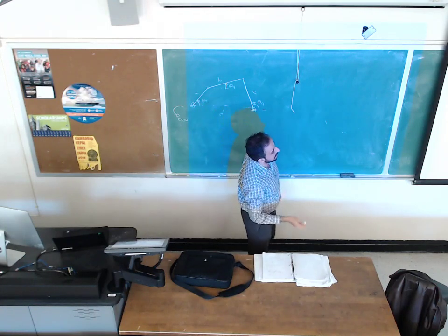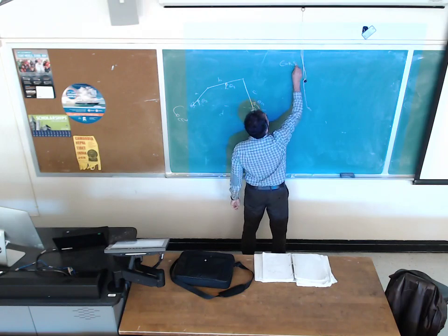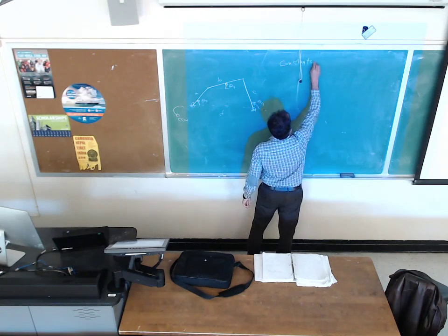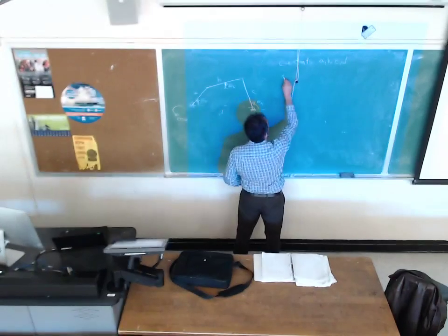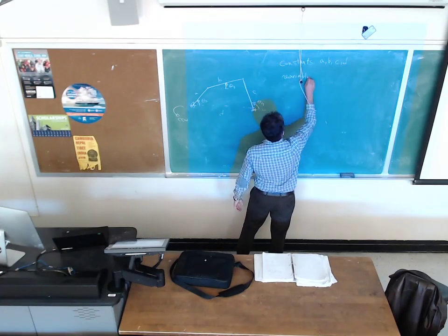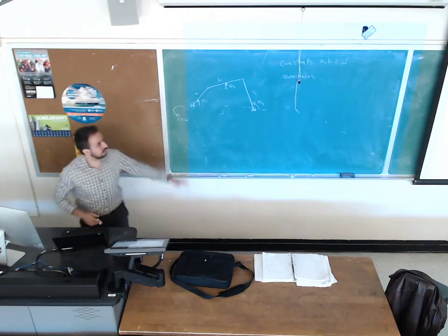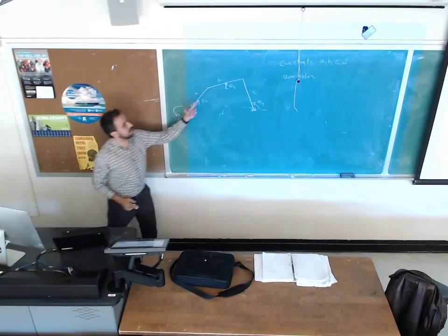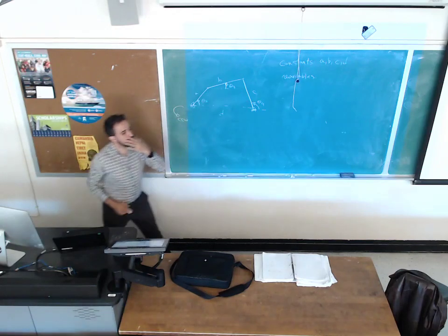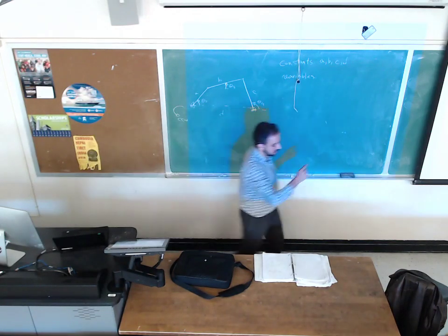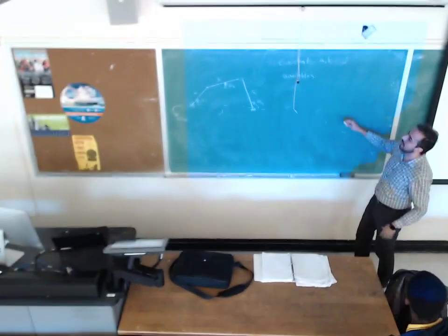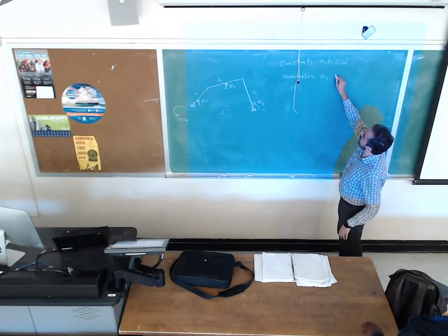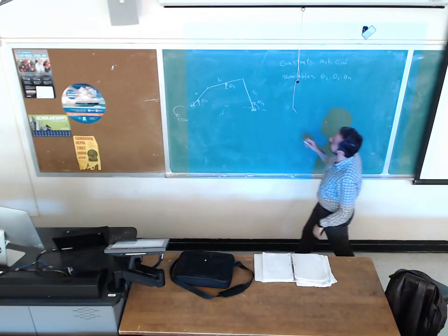For any displacement analysis, you need to have these terms. Constants: A, B, C, and D are constants because the length of the links are not varying. Variables: we have 4 links, 3 of them moving. Link 2, 3, 4, all 3 links which are moving have pins. So all variables would be the angles, theta 2, theta 3, and theta 4 representing them.